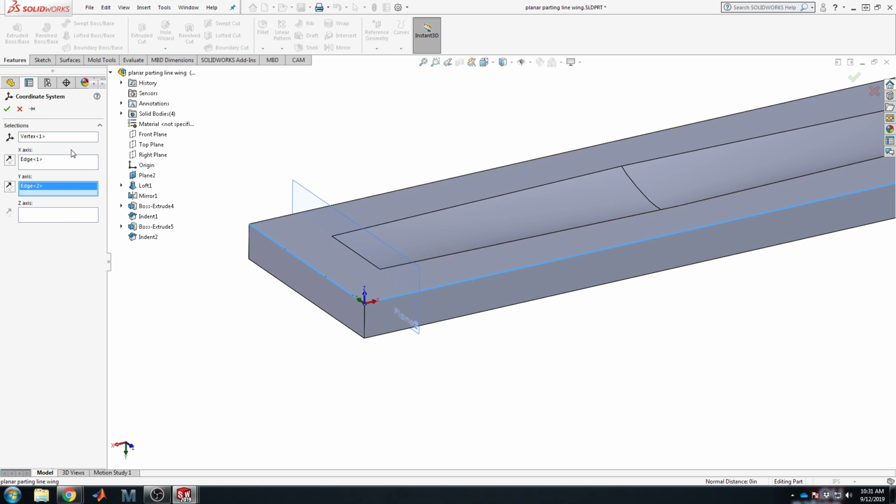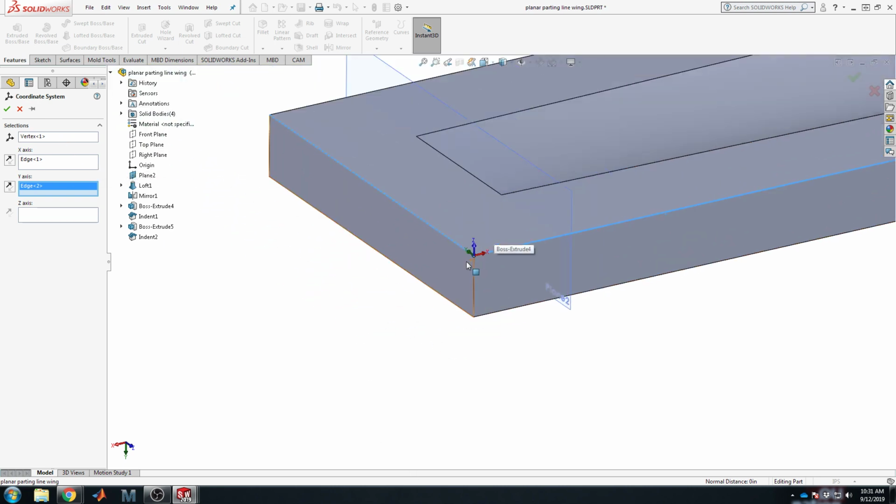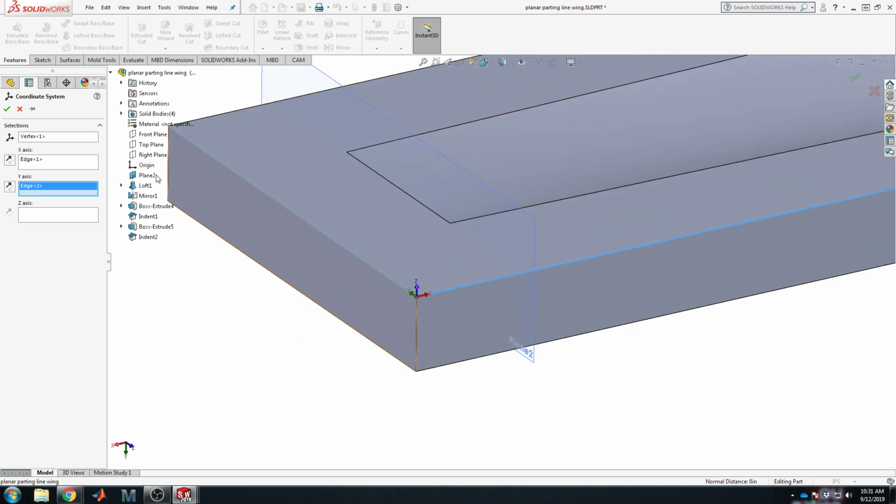And that's what I meant by you usually have to define 3 of the 4 elements, because, well, that 4th vector of the triad becomes set. If you did need to change that Z direction, you could change which direction Y is positive in. The vectors are pointing in the positive direction, and that combination creates the result of Z being positive up. So that coordinate system is what I want, and I'll say OK.